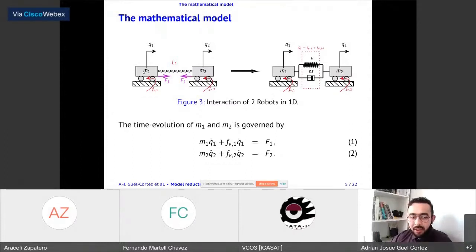So let's say that we have two robots and we need to keep them within a decided distance of each other. So you create some sort of operator over the error, computing and evaluating the distance between them, and that's going to create some forces that will attract them or repel them. If we have a simple PD controller, we can say that maybe we have something like a spring and a damper in parallel connecting the robots. And that's actually the mechanical intuition of what is happening when you add a simple PD control.